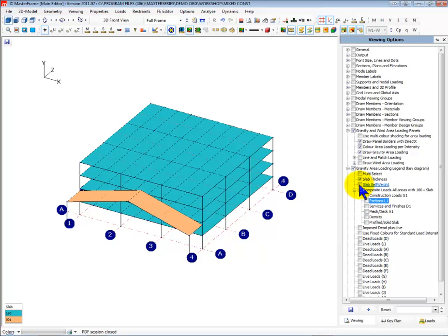But the self-weight is 0. Now you would have expected the 2.8 if this was going from 150. You would have expected a value of about 5 or 10 in here. You don't have that. It sees 1 millimeter as being nothing. So that is how you would do it. You actually put in 1 millimeter thickness for your slab as well.